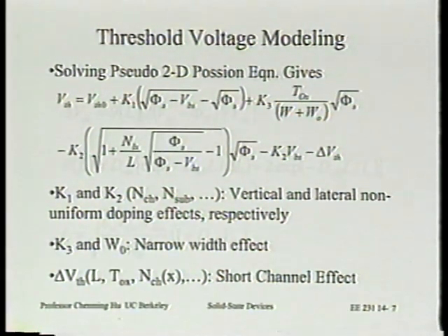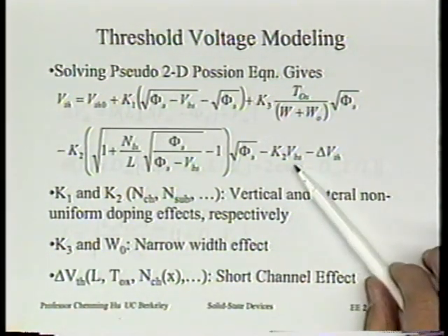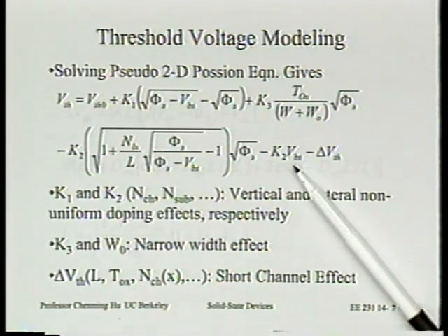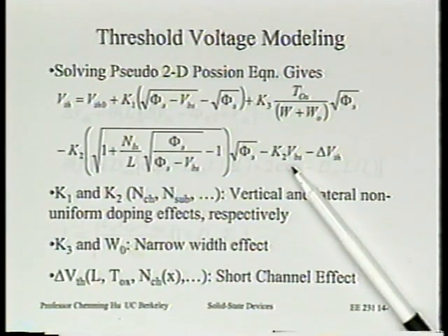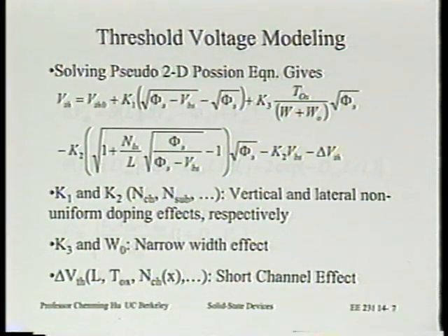Okay? I can give you a hint, you know. A lot of people thought, even today, I believe, they would think this is just an empirical thing because, you know, one would see that threshold voltage is sometimes a fairly linear function of VB. But actually, the students have thought about this many years ago, and they realized why the transistor should behave this way. And so that's why it's in the model, all right?